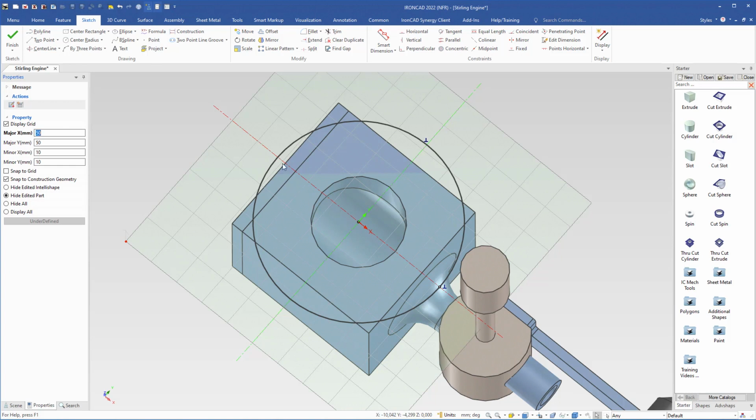And now we will project the top of the crankcase to the cross section. We come up here and select Project. We have two project commands, Project and Project Constraint. We don't need the constraints in this case, so we will use this command Project. And if we move the cursor to this face or this surface, we will see it will highlight in green.